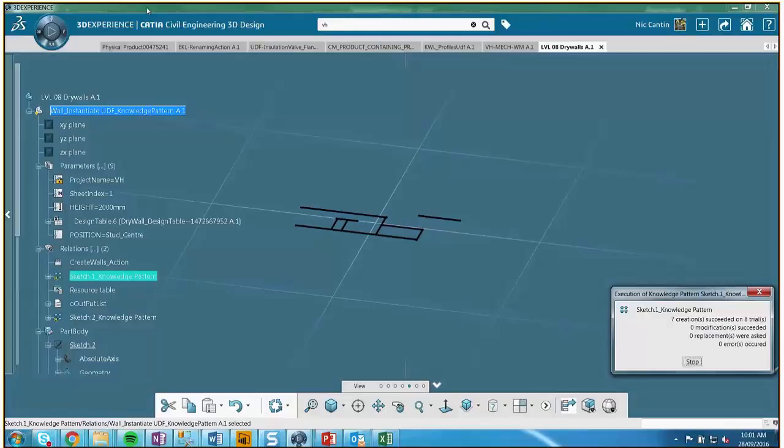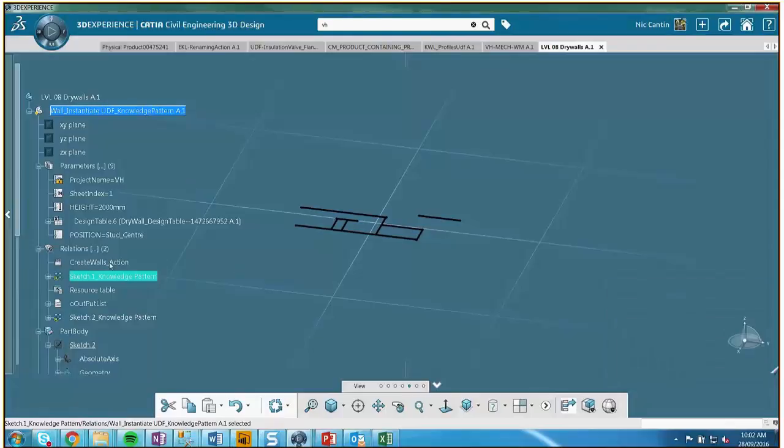For example, in this same Vancouver house project, we have headers that have inside corners, outside corners, and multiple canning for openings for ventilation, and that's managed all in one component family so that we don't have to generate and reference multiple component families at a given time. We just use a Boolean rule with if statements inside of that rule to manage each of the possible configurations, and you make one component family that drives all of those different permutations and instances.